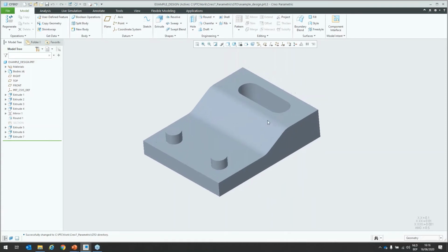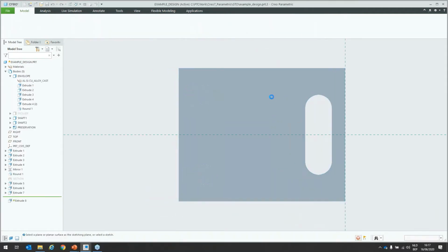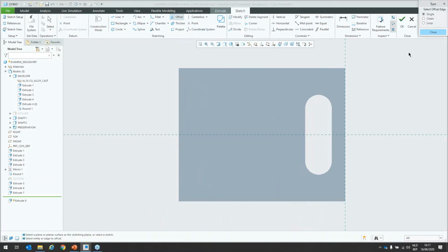So we'll start with what you see right here, and right at the beginning, I will create a new body. And what I'll do with this body is I'll call it the preservation body. So I want to keep all the geometry that should be preserved in this one. It's automatically activated for me, so all I need to do is create my volume. I'm going to use some of the existing Creo tools here to quickly offset some curves. And then we'll do the same for the internal curves just to project them.